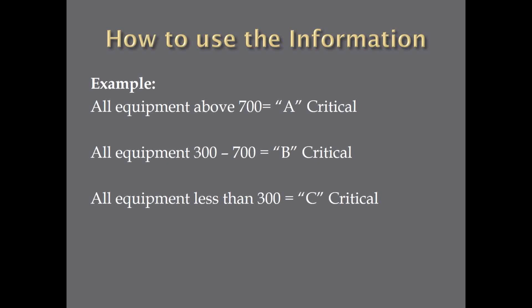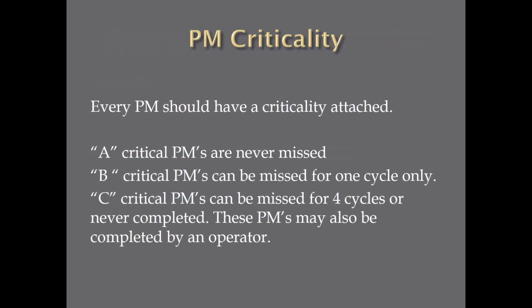We never did PMs on those. We'd have the operators check them. It took quite a few PMs out of our system. We were doing PMs on things that were not critical in any way. So this is the plan we used right here. It became very effective. We had less failures. We never missed PMs on critical equipment.